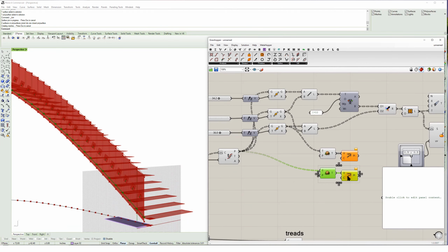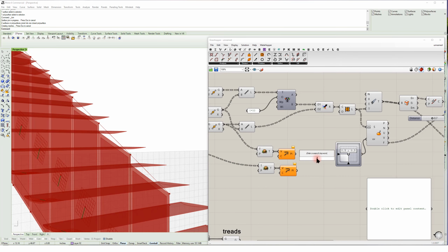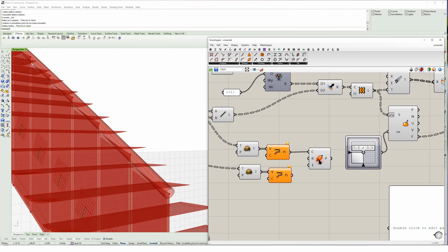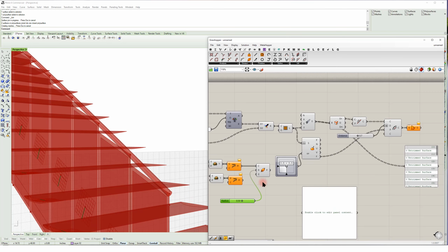And now to get some geometry, let's just pipe it. So pipe, input a curve, and the radius, we can do flat or rounded caps, do flat. And I'll set the radius to be, let's do 0.5. So it's going to give me a 1-inch diameter. And there you go.